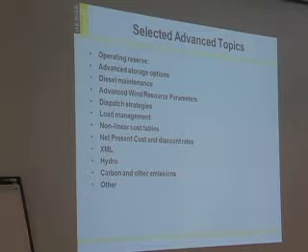Advanced wind resource parameters: everybody's familiar with the Weibull K, I think, a really standard statistic that's used to describe the wind resource. In Homer, we also have something we call the autocorrelation factor, which is not as common, but is very important for systems with storage, or off-grid systems, or systems that have to stand on their own.